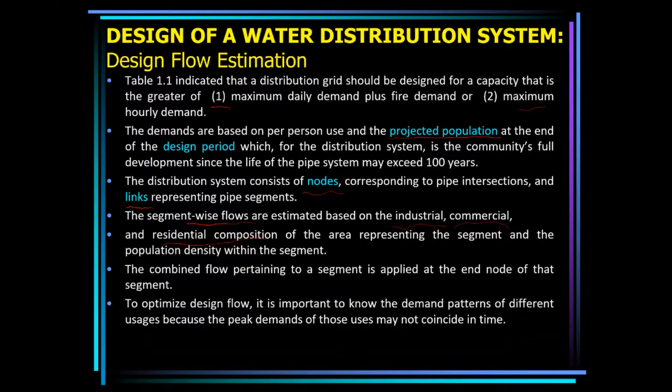To optimize design flow, it is important to know the demand patterns of different usages, because the peak demands of those uses may not coincide in time. You need to know the demand patterns, because more often you have a rush hour early in the morning, everyone trying to bathe, go to work, go to school, and all that.